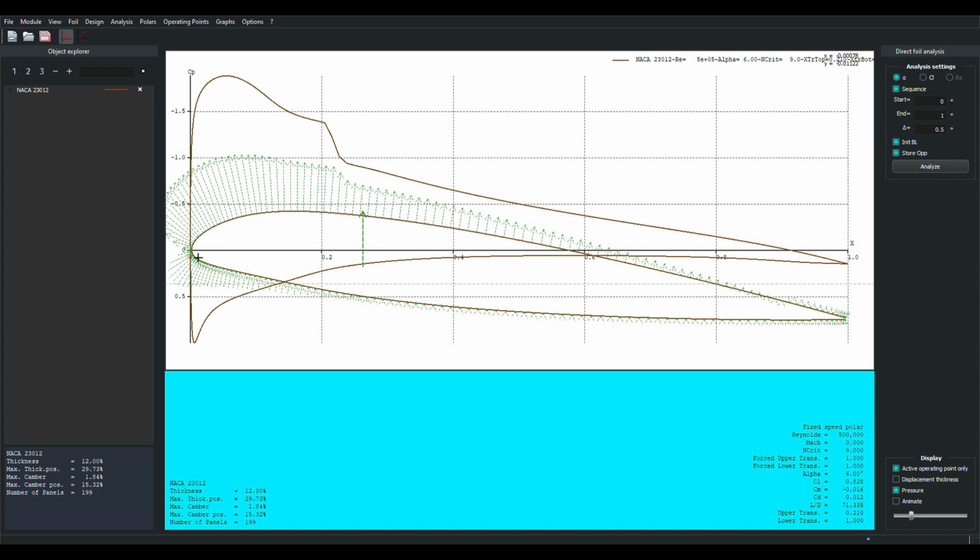You know, they come in at one speed, 20, 23 miles an hour, and then we speed them up by making them go uphill, and because of Bernoulli and its incompressible flow, they have to go faster, and the pressures drop, and we get lift, the magical lift that we're looking for to fly. But eventually we have to pay the piper, and we have to give it all back.